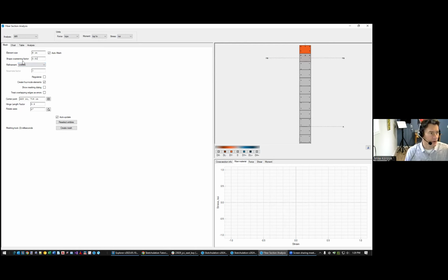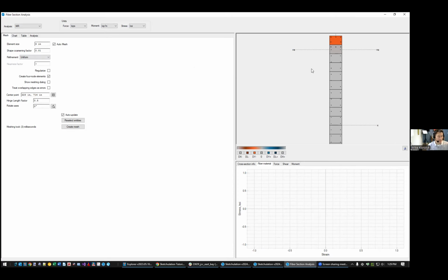The meshing algorithm will coarsen shapes. This doesn't apply to a rectangle, but if you had a very complex shape, it does some initial coarsening of that shape so that the mesh doesn't get out of control. There are a few different refinement options: uniform, near points, or none. When the meshing algorithm runs, it creates an initial mesh, which is the most coarse possible, and then it goes through a refinement step. The uniform option is going to give you probably the best uniform mesh, but near points basically does tighter meshing near edges.